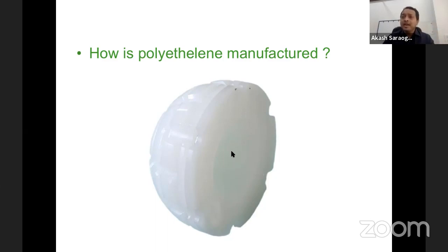We also gamma irradiate the plastic to sterilize the plastic. So suppose we have packed the plastic into a box. Now we need to sterilize it before we use it in a patient. So again, the entire box assembly goes for gamma irradiation. Now remember, the first gamma irradiation that the plastic received was to change the composition or the chemical bonding of the plastic. So the dose was much higher. Whereas for sterilization, the gamma irradiation dose that we use is much lower.